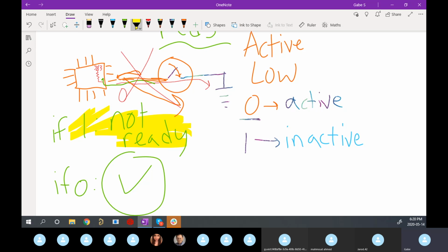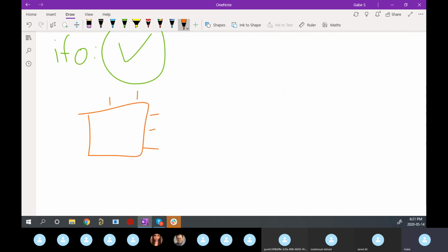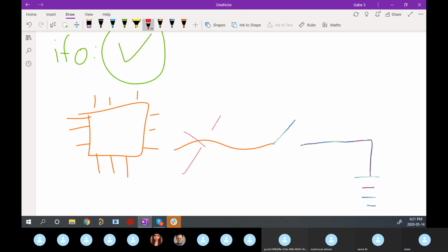Let's say I didn't have that pull-up resistor, right? Let's say I was like, I don't need that. I don't want to write that extra line of code. It's a waste of my time, right? I don't care anymore. I have my microcontroller, right? And then it's connected to my switch normally, so something like this, right? Now it disconnects, but I have no pull-up, right?